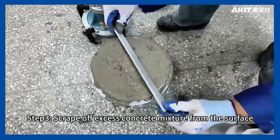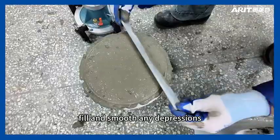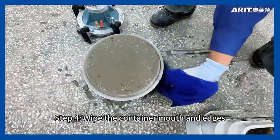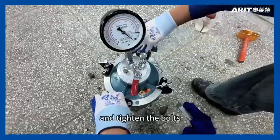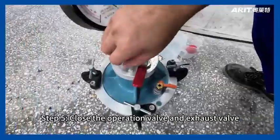Step 3. Scrape off excess concrete mixture from the surface, smooth it with a trowel, fill and smooth any depressions. Step 4. Wet the container mouth and edges, cover with the lid, and tighten the bolts to ensure a sealed and airtight fit.